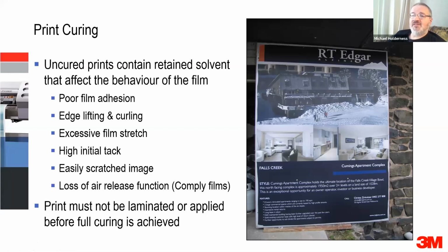Now, you'll probably find some great settings that work on vinyl, and you'll find that you turn those down if you're printing on paper, or you'll turn them up if you're printing on banner. And that's purely because of the weight of the media or the amount of ink ingress into the media. It's going to depend very much on what you put through it.